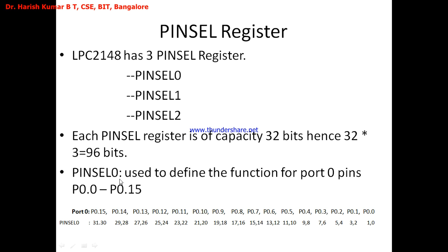That means using the PINSEL 0 register, I can define what function the pins of port 0 should perform. Now port 0 pins, that is again from P0.0 to P0.15. Using this register I can tell what function each of these pins from P0.0 to P0.15 has to perform.